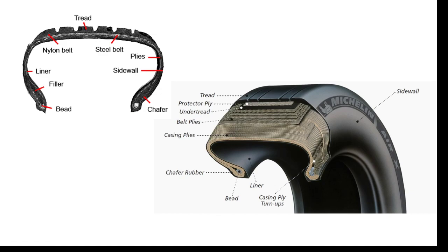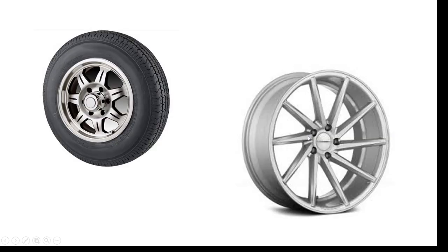You know where the center and the longitudinal axis are. In sketch mode, draw that axis, and then showing this profile as the region, apply the revolve process. This means you created the main part of the tire. The rest is the tread creation stage.